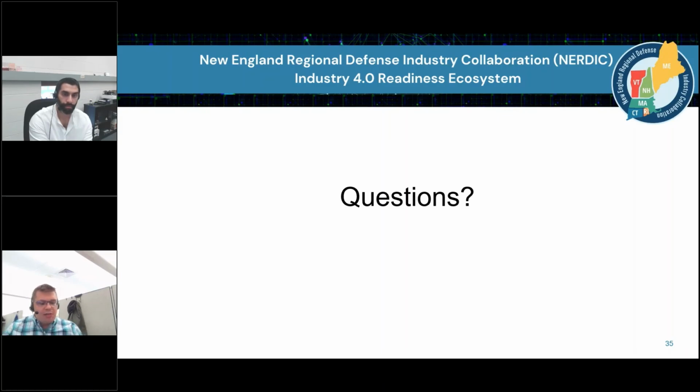That being said, if payload is really an issue, there are other ways to get collaborative behavior out of standard industrial robots. We briefly mentioned at the beginning the several main classifications of collaborative robots, and most everything these days is focused on power and force monitoring. The other main type, though, is speed and distance monitoring.